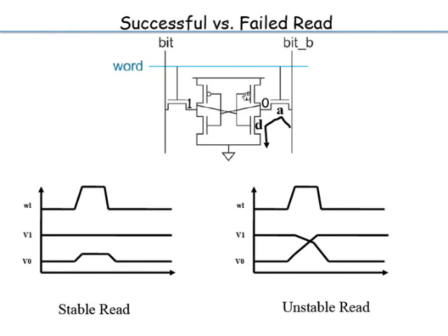Unfortunately here it's mirrored. So on the right side is the node where the voltage is 0, so I'm also calling it node 0. The node 0, which is the Q from the previous slide, goes up by a small amount, and of course the bit line discharges, in this case bit bar discharges, and you get the data out. Then when the word line is shut off, everything gets restored back to what it was before. Okay, V0 goes back, V1 remains where it is.